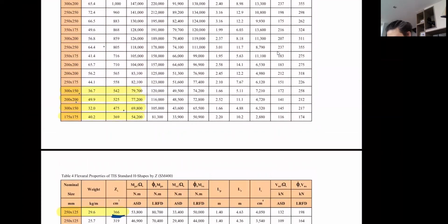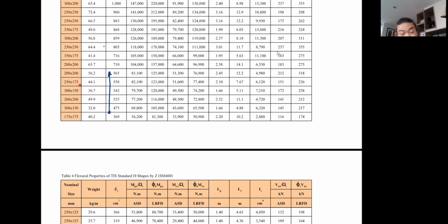You can use this, you can use that, you can use anything going up there because it's above 389. But the point is, it's only this one that fits the depth criteria. This one will exceed the depth criteria, and this is a column section. It's not a good idea to use this column section, and besides they are heavier as well. So we are left with this.